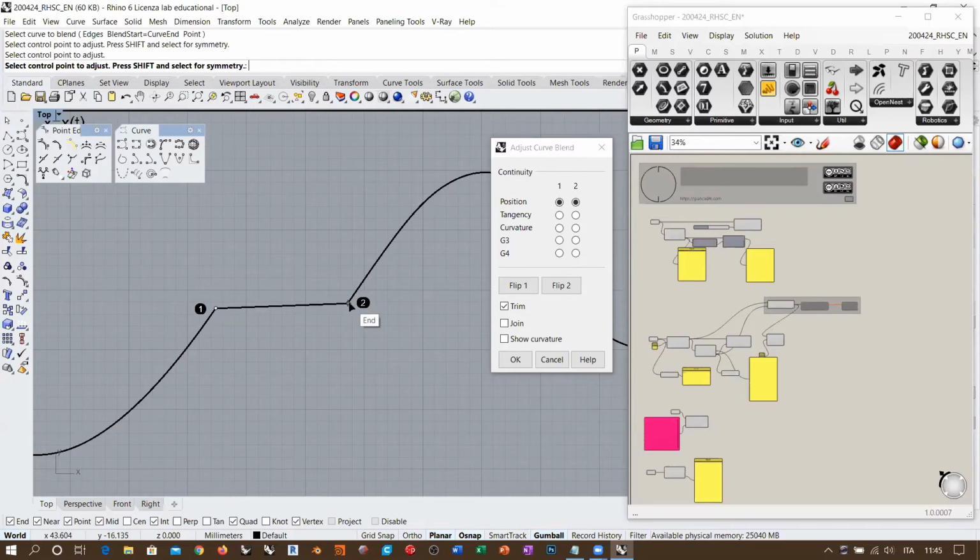And so the result is going to be a straight line with two control points, which, by the way, is going to be straight and linear. Straight because of the shape, linear because if we have a control point curve with just two control points, the degree of this curve is going to be 2 minus 1, so degree 1, which is a linear equation. So we have a straight connection with degree 1, straight and linear, right? Which is the simplest connection possible.